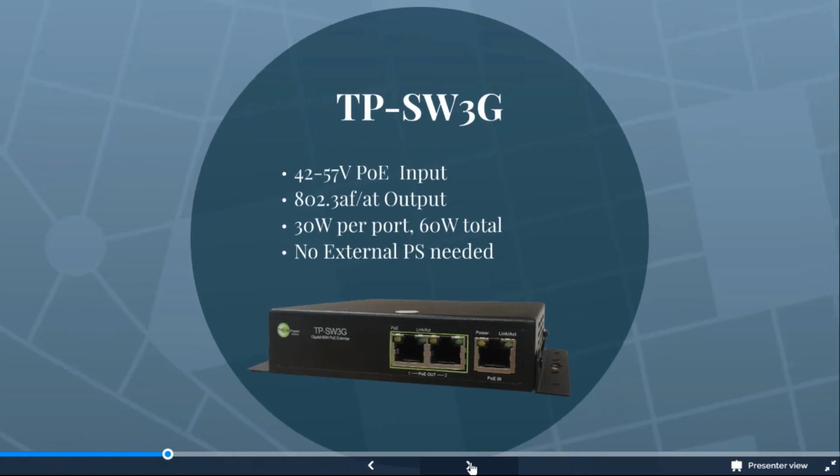So when we started, we designed several different products, and we'll start from smallest to largest. We call this our PoE extender, or our 3-port PoE switch. This is a 48-volt input at 802.3 AF or AT, so up to 30 watts. The maximum distance you can run Cat5 cable is 100 meters. At 100 meters, you would either need to have your equipment plugged in, or you would add a PoE extender. And that's what this little switch does.